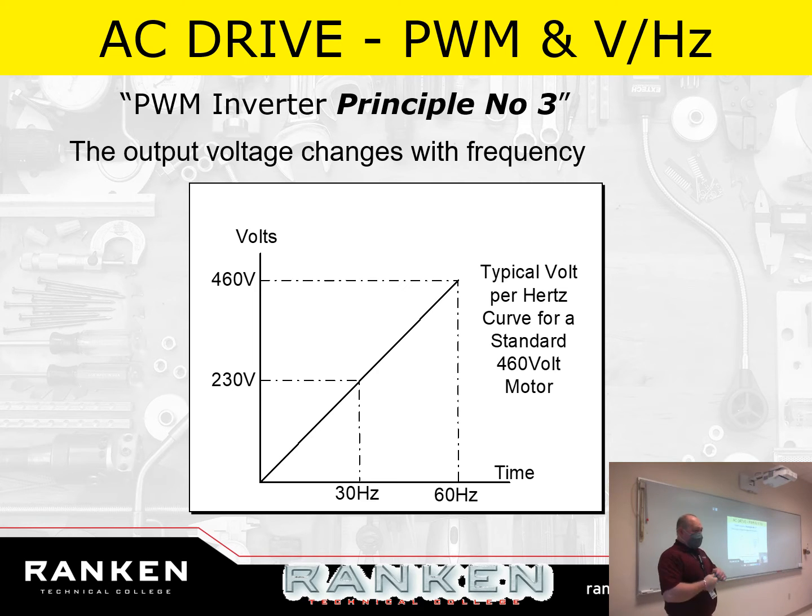So, on this variable frequency drive, you have your DC bus. You have access to the DC bus voltage, positive and negative. That's this right here, okay? So, if you have an IGBT, a transistor, and you measure from the positive side of the DC bus to T1, it should act like a diode, like a solid state device.